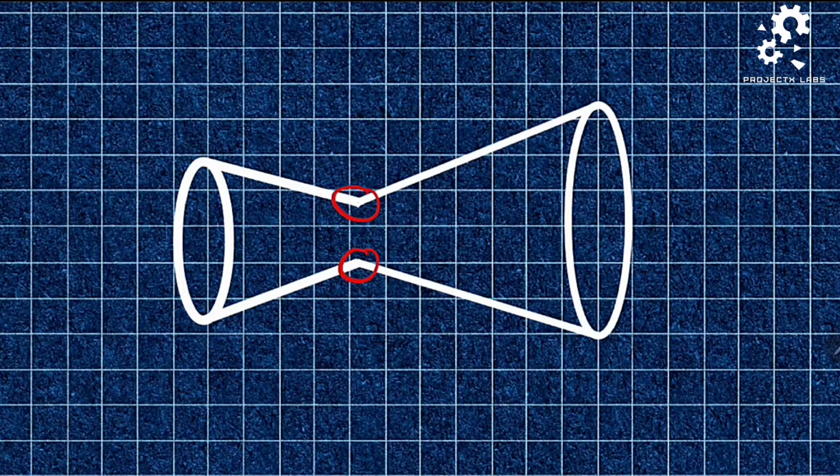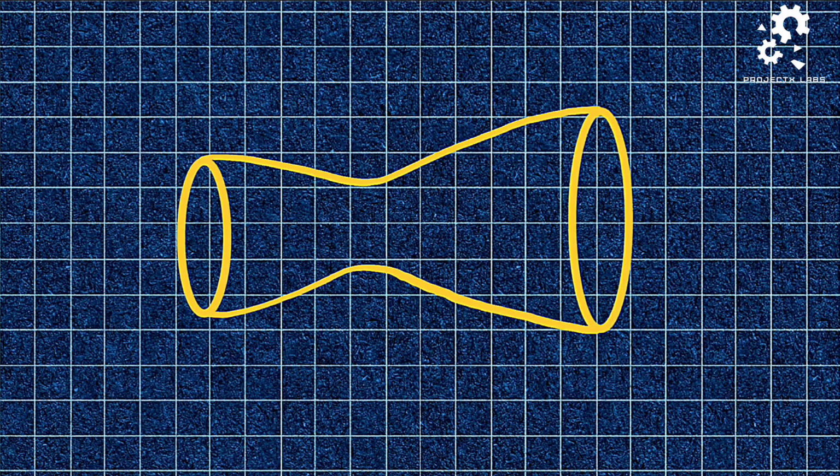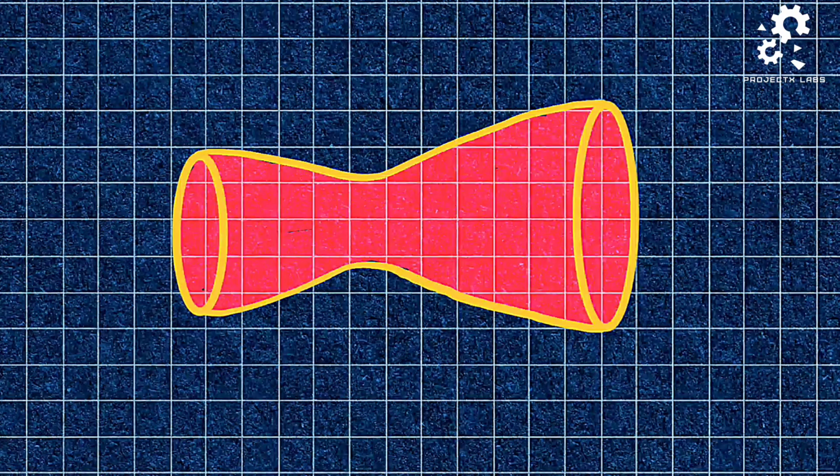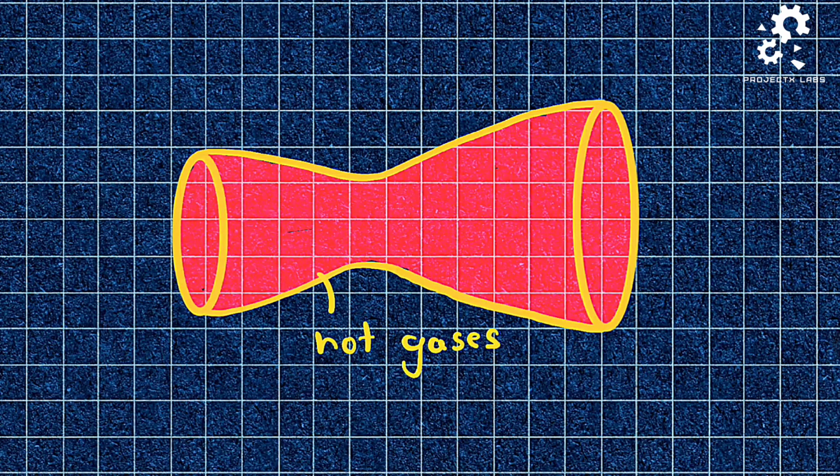In reality, sharp edges are not suitable for high-speed flow, which may result in shock waves that may block the nozzle. So, the converging section will curve gently into the throat. Then, the curve will turn into a diverging one, allowing smooth transitioning to the cone, resulting in a curve-shaped nozzle.